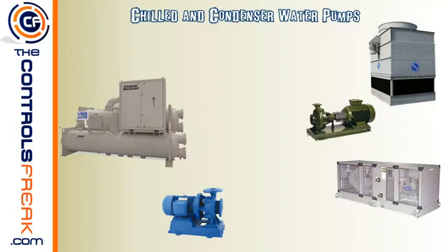We've already talked about the chiller here, and we've also talked about the cooling tower. Some other little items besides the pumps that we put here is the air handler. This is an example of a packaged unit air handler that would be inside the building, and you'll see the little pipe connections here, and that's the cooling coil that's inside the unit. This green pump is going to represent our condenser water pump, and typically they use green piping or green to represent condenser water. And this little blue pump here is going to represent our chill water pump, and they usually try to use blue or white for chill water piping as well.